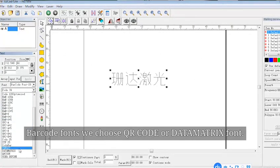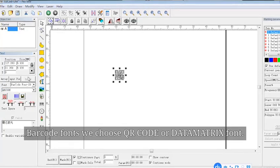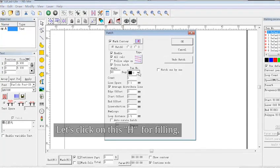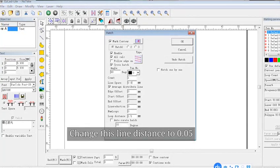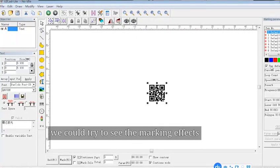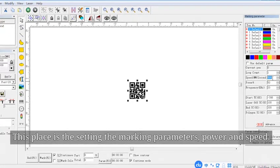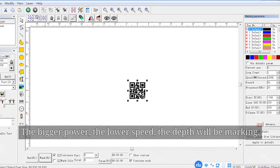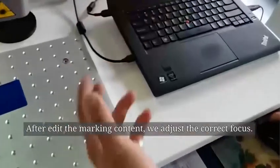For barcode fonts we choose QR code or data matrix font. It will automatically generate a QR code. Let's click on this H for filling, and change the line distance to 0.05. We could try to see the marking effects. This place is for setting the marking parameters, power and speed. Frequency is fixed, no need to change. Speed could be set faster, 2000.